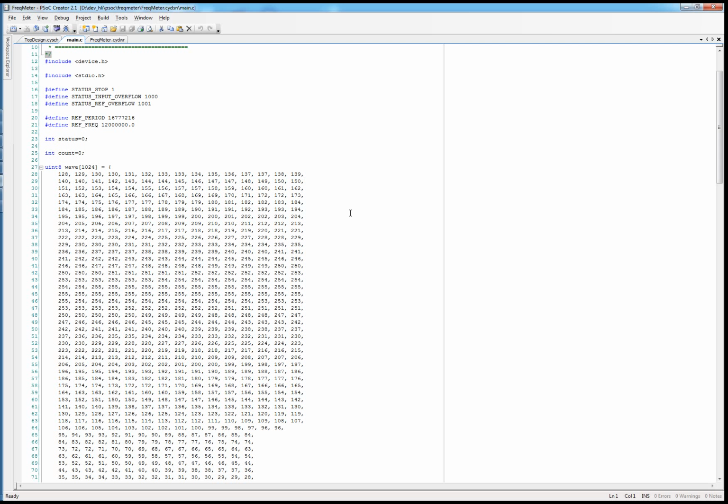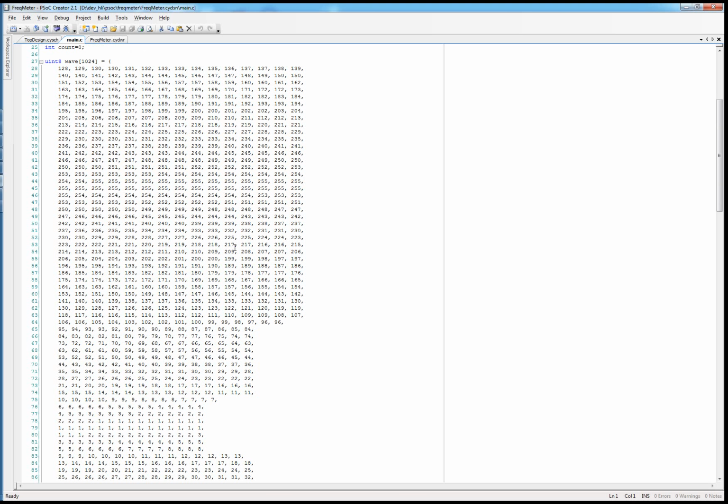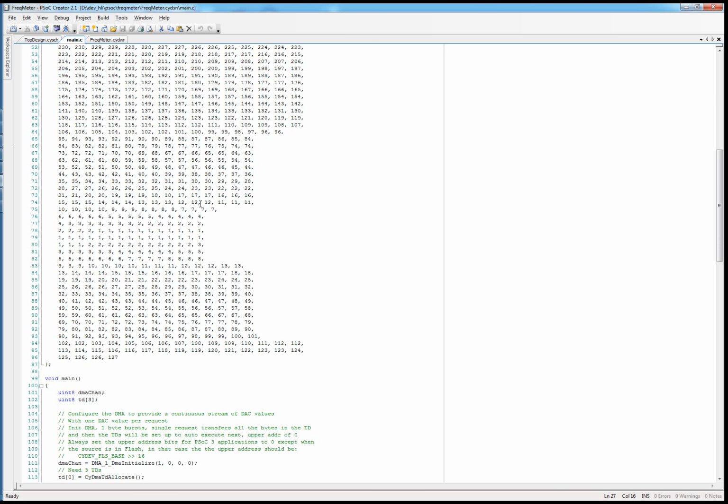From a program perspective, what looks different here is we have a much larger waveform table, because when using the phase accumulator, you can actually skip values in here. So even when this is 1000 samples large, you can choose for a higher frequency to skip 9 out of 10 samples, meaning you would choose every 10th of them and create a different frequency from that.